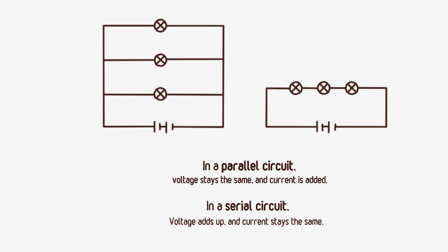So in this example, when we put 3 solar panels in parallel, all the positives are connected together and all the negatives are connected together, and they come together at a single spot. I stole this picture from Wikipedia. I'm just trying to simplify it, and it serves my example. So in a parallel connection, all your positives are connected together, all your negatives are connected together. It's a lot more wiring. The good part of this is you keep voltage the same and the current actually gets increased.